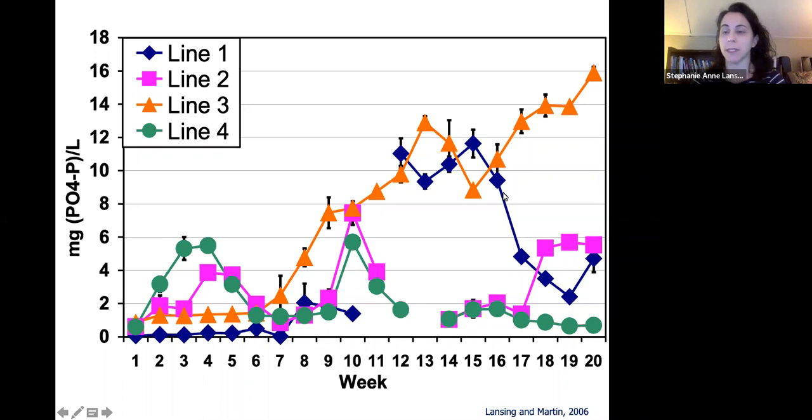And what we found is that in our final wetlands, where we were getting a lot of our phosphorus removal, some of them had a preferential flow pattern. And so we were having some of the phosphorus in some of the wetlands where we could kind of see breaks in the wetland where the water was moving through. So you really need to think about how that wetland flows and making sure that you're using all of the surface area of the wetland for treatment.